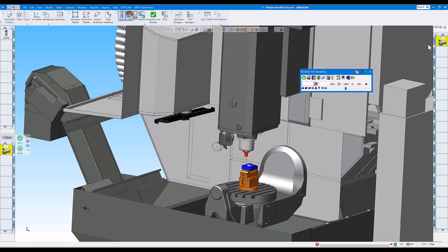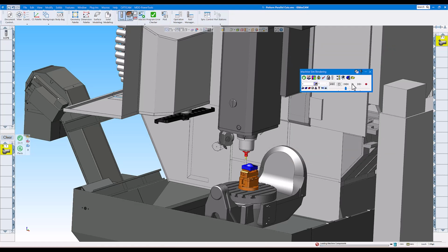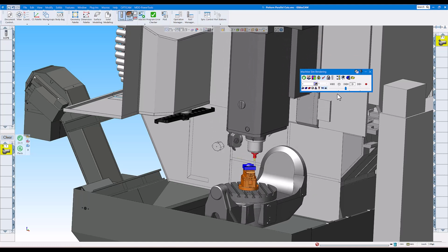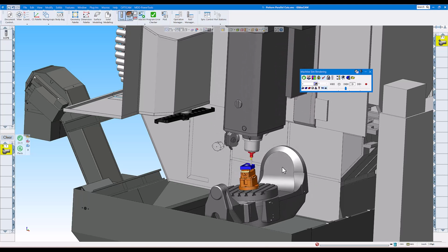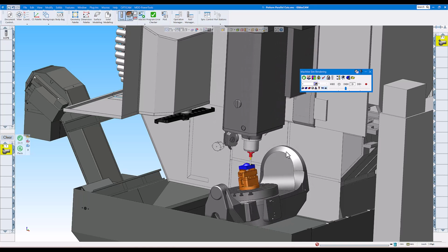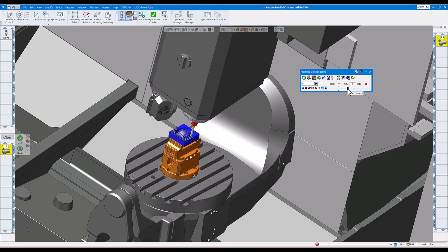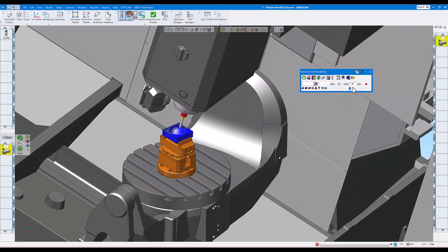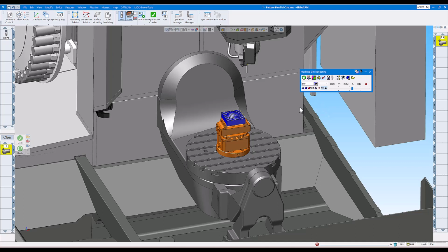And you can also look at that under the operation data, so you can change this for each operation to be differently. But you can see I can do B+, B-. So if we have this on B+, rewind it, play again, and you can see it's going the opposite direction. So you can force it to go in the negative direction or the positive direction on the B axis here. Of course, C, we usually leave that unlimited so it can go where it needs to. So that's our first pattern cut called pattern parallel cuts.